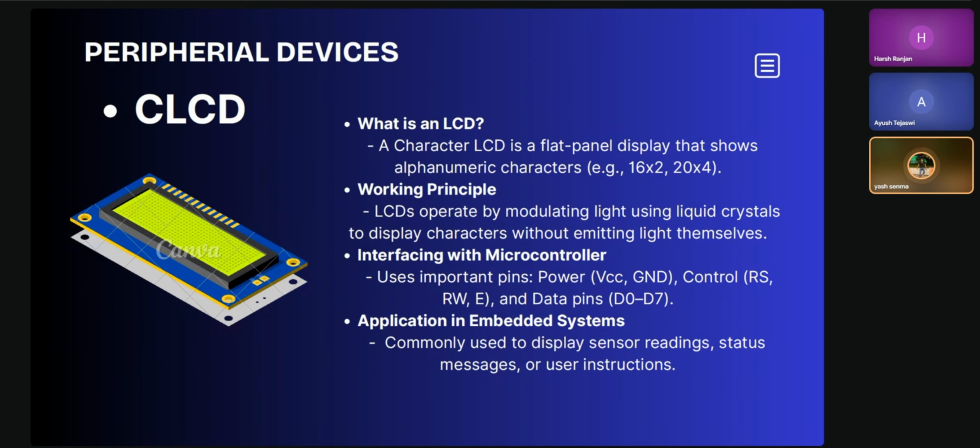We use custom functions like lcd_cmd and lcd_data to handle commands and data. The LCD not only enhances the user experience but also helps track the real-time process flow for each operation.